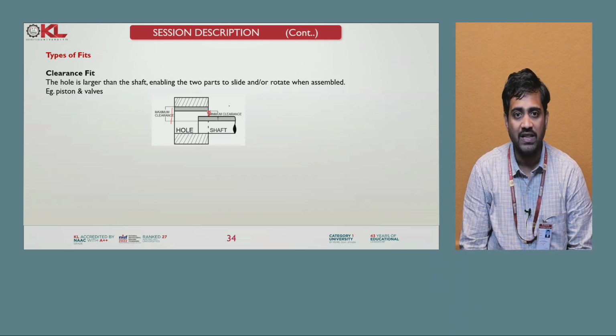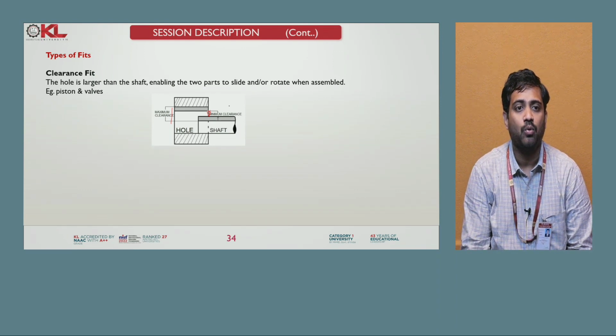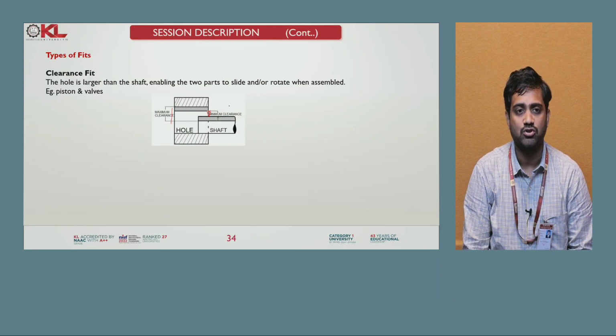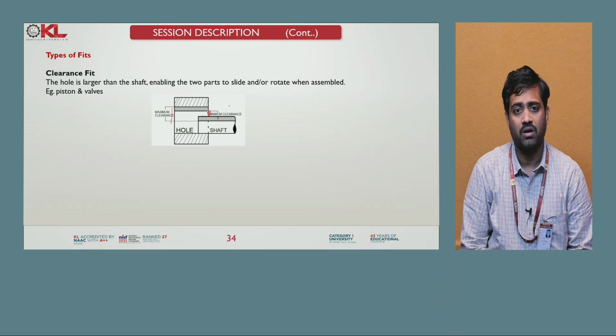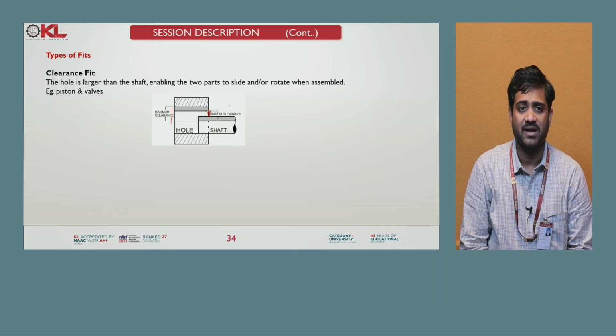With the clearance only, the piston can move freely, and also the valves, the inlet and exhaust opening valves, only if you give the clearance can those slide or move. Whenever there is no clearance fit, definitely the piston or the valves can't move freely, they can't slide.